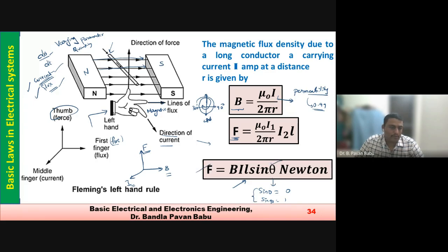If you want to know the force developed at a particular angle, then we can use this equation. Here I represents the current flowing through the rotor circuit. Why have I written I2? It is the secondary, or the rotor, current. We are concerned about the current flowing through that particular element. Two parts will be there, basically stator and rotor, and we are concerned about the rotor current, which is the secondary current. Once I discuss DC machines, I will make you more familiar with this. Just try to understand, these are the very fundamentals. And 2 pi r, where r represents the radius of that particular conductor.